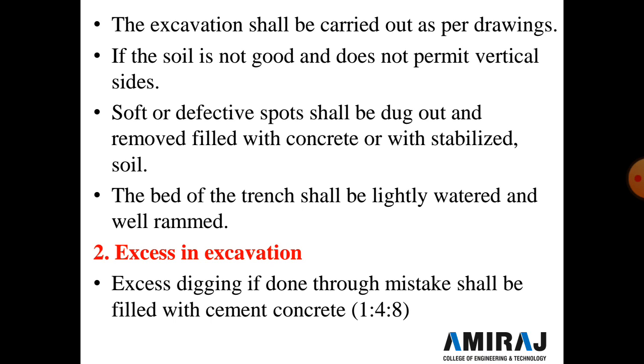If rock or boulders are found during the excavation, these should be removed, and the bed of the trenches shall be leveled and made hard by consolidated earth. The bed of the trenches shall be lightly watered and well rammed, and foundation concrete shall not be laid before inspection and approval of the trench by the engineer in charge.